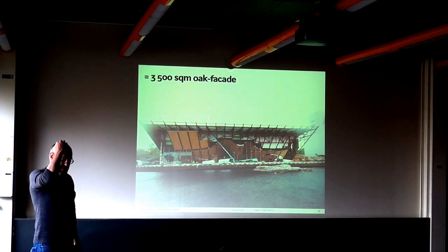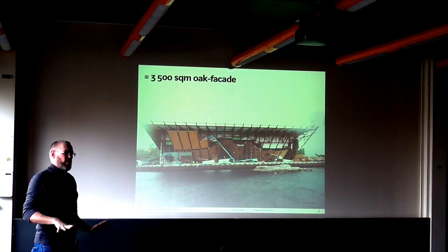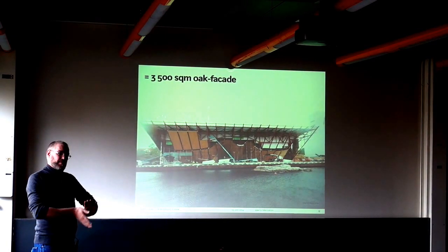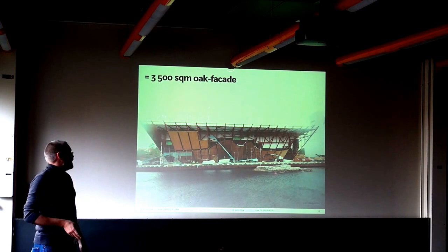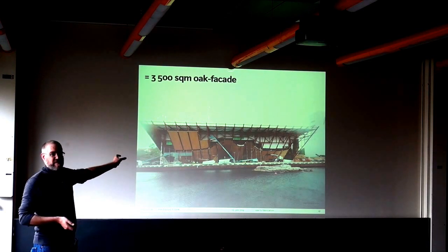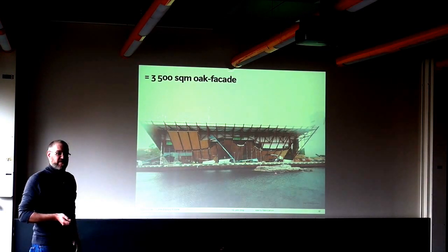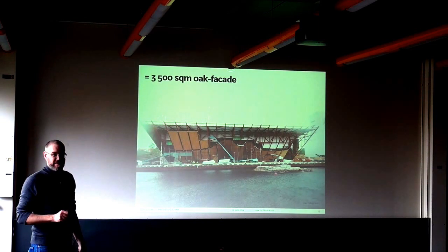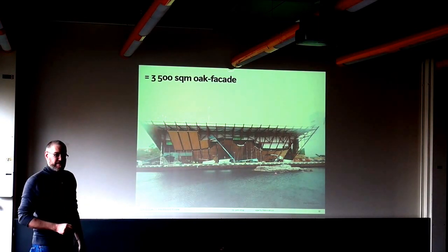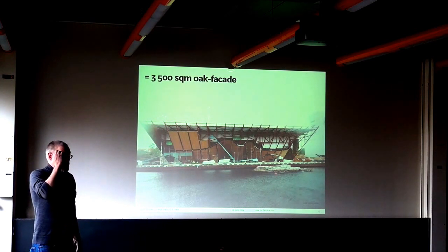And we had a design surface by the architects, which was almost all right to do the planning on top of. And then basically we had to put two things together. First, by coming up with proper details together with the timber engineers that would allow us to take the plus minus 50 millimeter tolerance that was in the steel structure down to plus minus 1 millimeter that we needed in the facade to get those gaps running in straight lines, and a few other things.